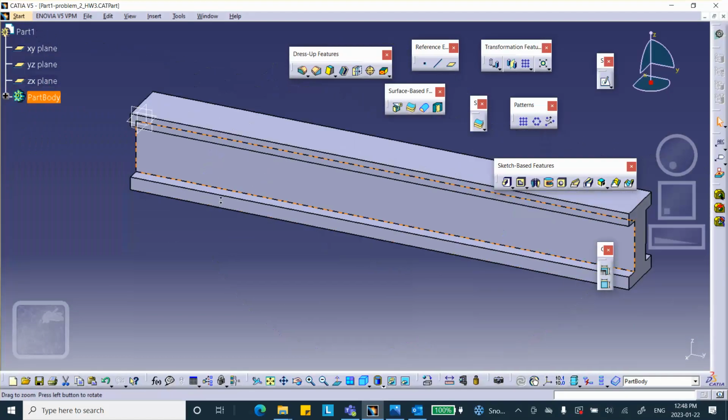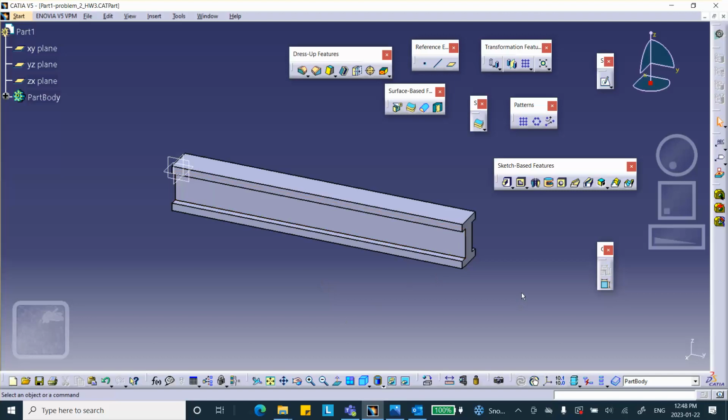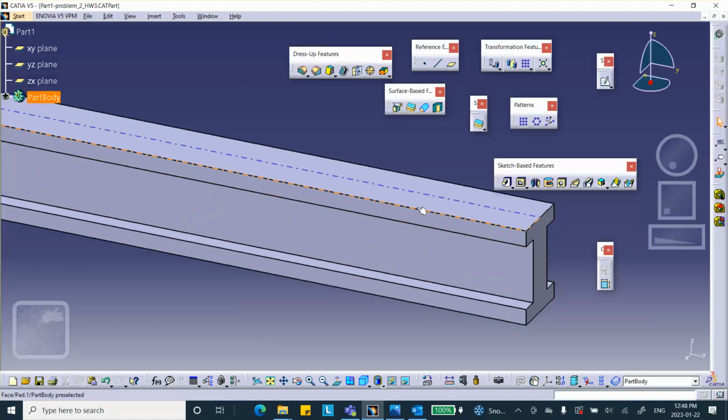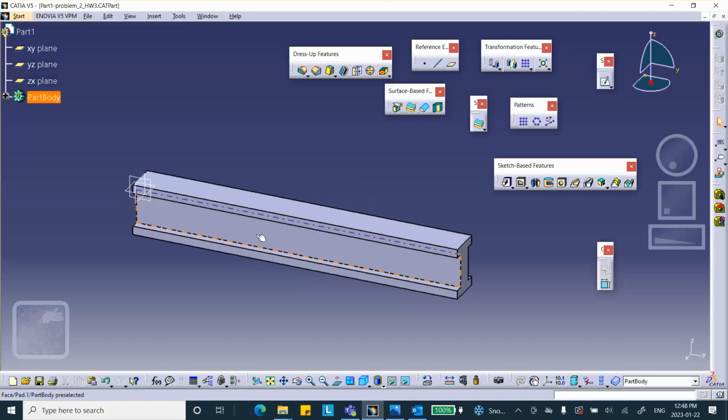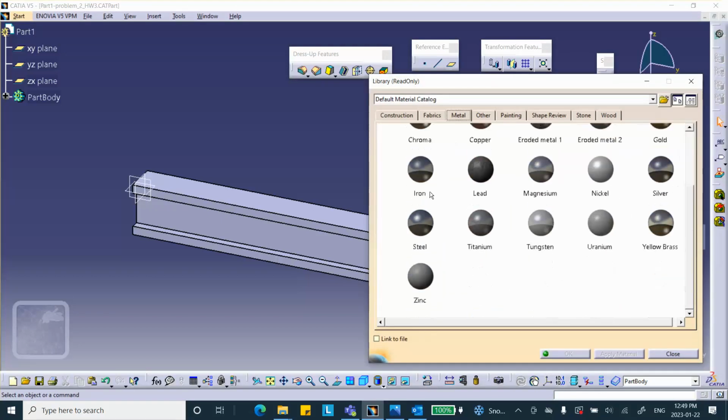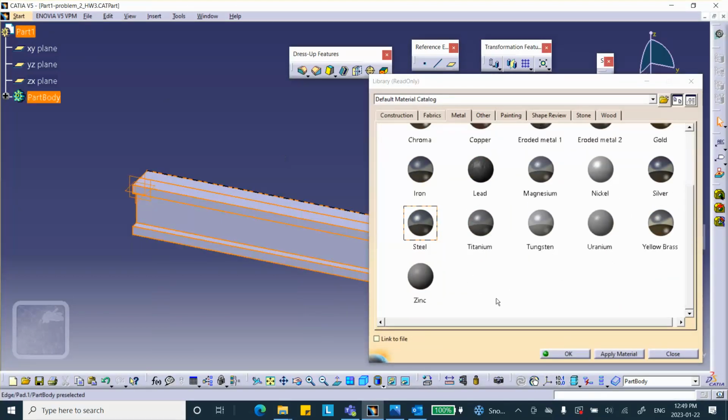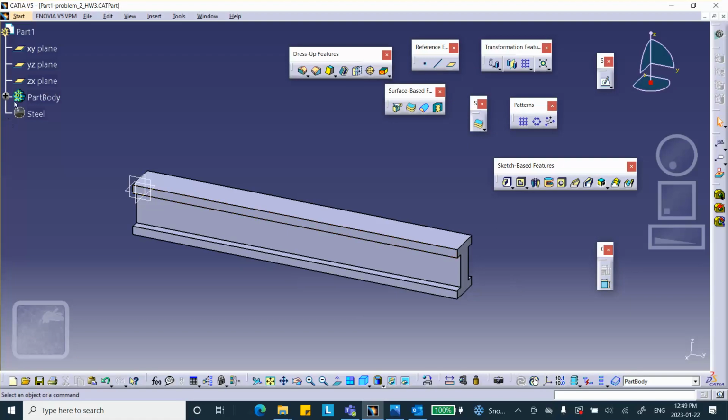There. Now, we're not assessing accuracy in these problems. That's why, because probably the stuff that we're going to get as far as stress distribution around these edges is going to be totally nonsense, okay? Because you have to use a fine mesh in order to resolve that stress distribution. In fact, the fine mesh relatively everywhere close to these discontinuities, but I'm not going to do that, okay? So let me apply material properties of steel metal, because whatever I'm giving you in that handout is close to steel. There we are.